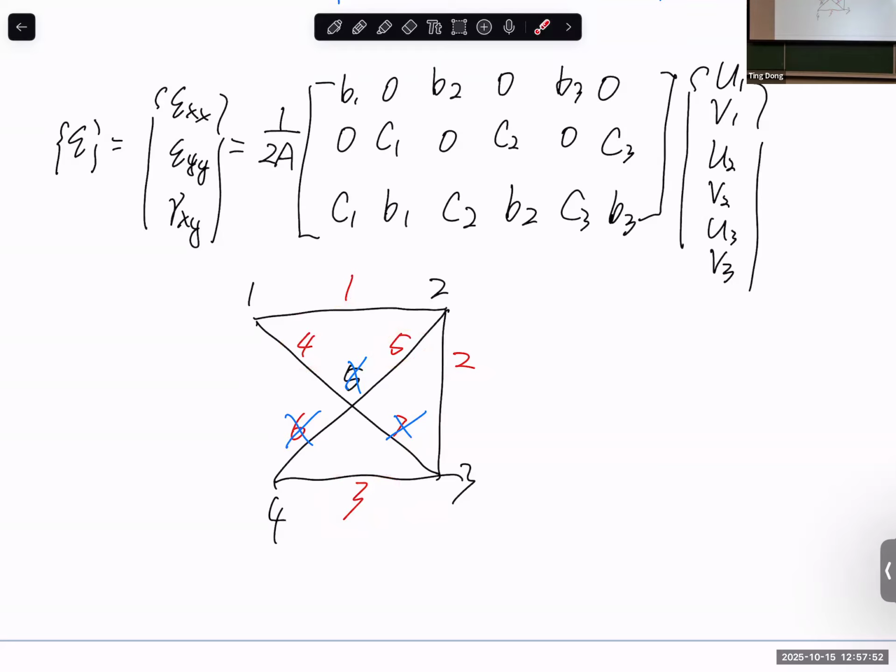And the same thing for node set, but node set probably does not affect much here, because let's say the original input file generated from Abaqus, probably they put these 2 in one node set, and I say, okay, I apply force. So I have the F1 1000. It basically 1 means in the x direction, 1000 means magnitude, right? So it means that these 2 nodes are put in the same set, node set 1, and force applied here.